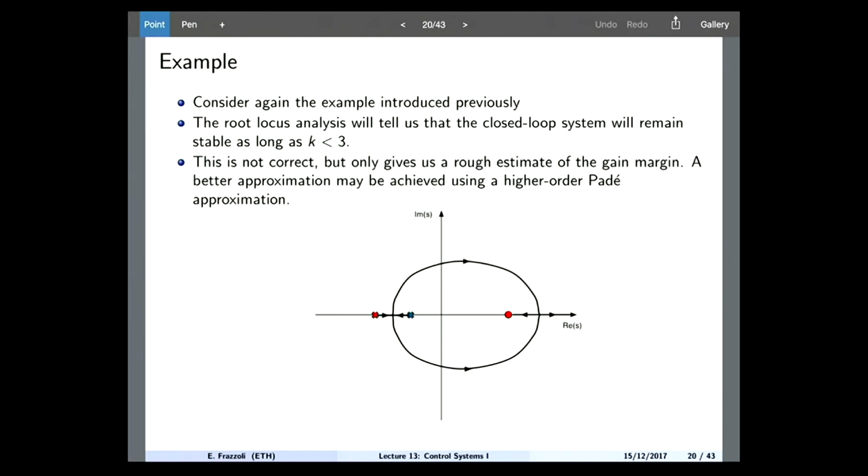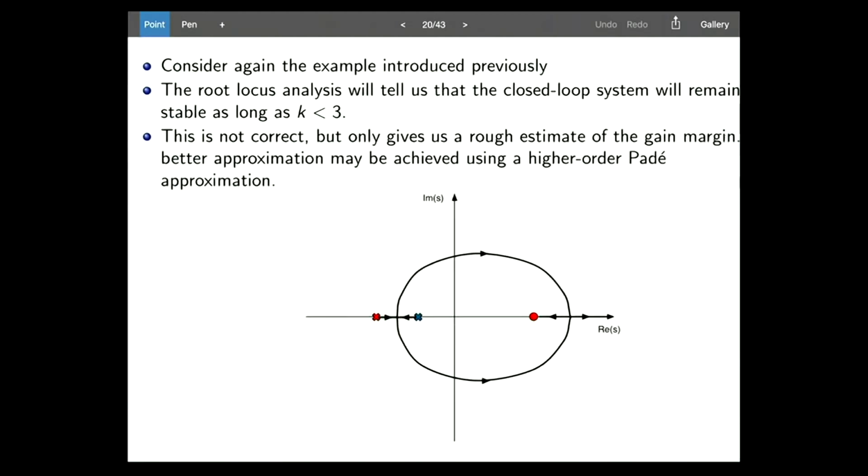Now the root locus is not only going to the left to infinity, but these two poles meet up here in the middle, split off, and become complex conjugates. Eventually, for high gain, one of the closed loop poles will go to the open loop zero. The open loop zero is a non-minimum phase zero, meaning that as you increase the gain, that closed loop pole will become unstable. The other root will go to infinity.